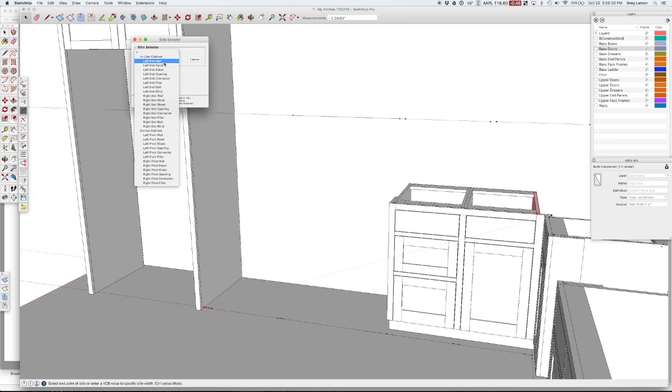I'm just butting straight up against this. I just want it to be a 1.5 inch wide style. Certainly not a panel. It's not a sheet. If I do an opening style, I'm going to get this little filler piece here. If I do a connector style, I'm going to get holes, assuming I connect to another cabinet. A butt and a blind are going to give me too wide of a style and extra characteristics with toe kicks that I don't want. So that's why we provide this filler style.